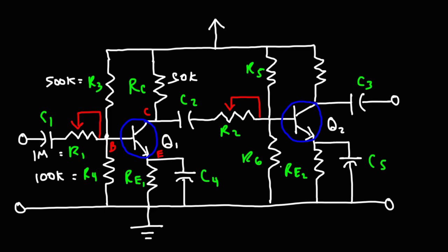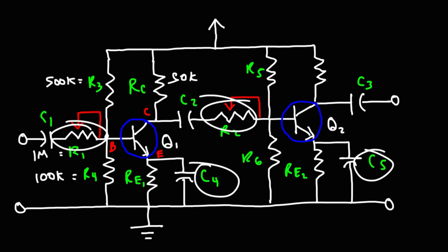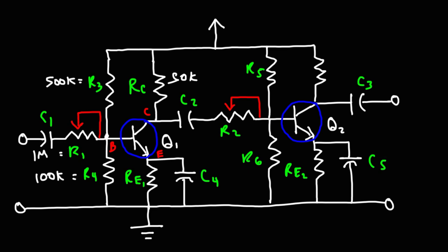So it's important to understand that adding C4 and C5, there's a trade-off. You'll increase the voltage gain, but you could potentially introduce distortion. But if you do introduce distortion, you could reduce the voltage by using the potentiometers R1 and R2. So that's the purpose of C4 and C5.